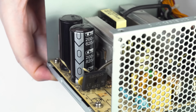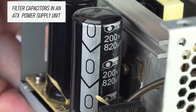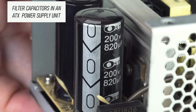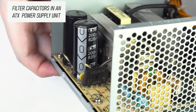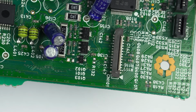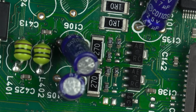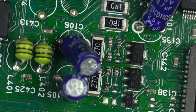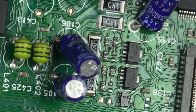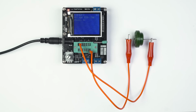At the same time, they are simply indispensable as filtering devices, and in most circuits they can be found connected in parallel with the power supply. Such capacitors ensure stability, minimize voltage transients, and may temporarily take over the power of the circuit in case of short-term voltage drops. In this situation, a parameter called ESR is of vital importance.